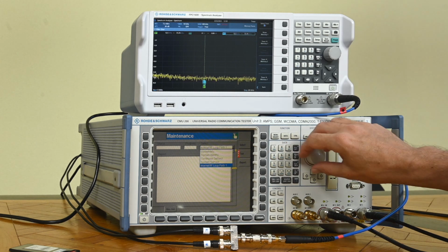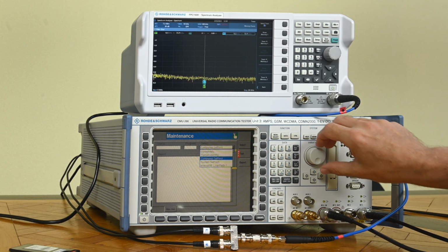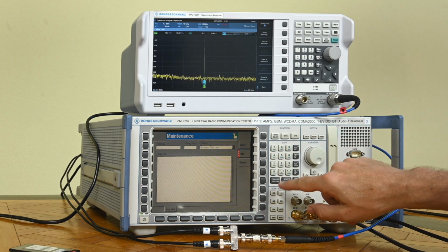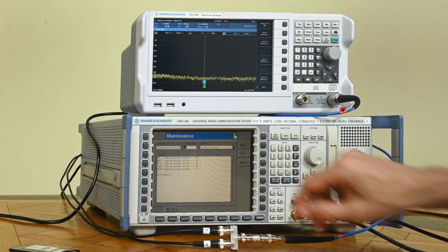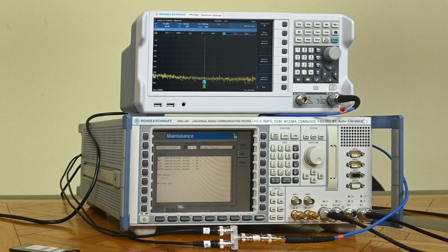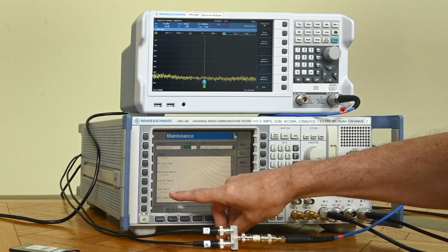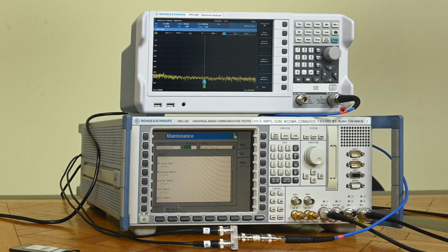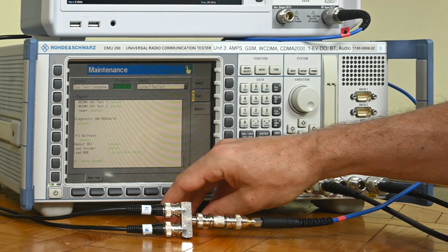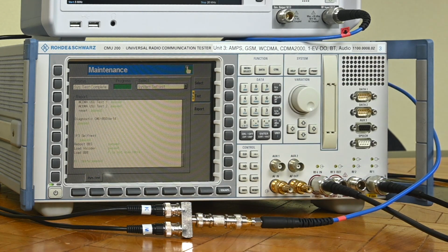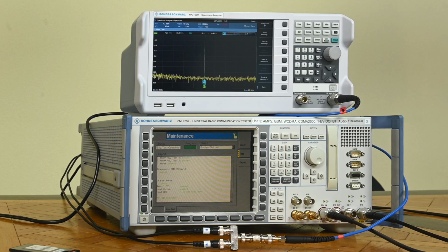Another thing we can do is an overall system self-test. So that's going to be here. I'm going to run it now. And EEPROM is tested. I think that's already what we just did. We're going to get a couple of other things. Let's just wait until we get to the IQ board. IQIF board passed. So everything looks fine in the internal system self-test. Okay, I waited all the way to the end, didn't want to stop it. We also see IF3 self-test passed. All tests passed properly, so the unit seems to be in a fair state.